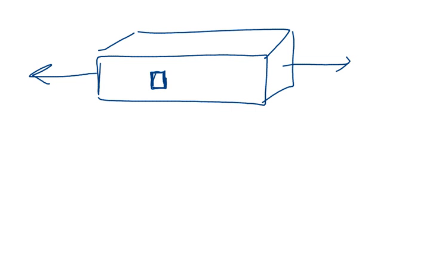But if I happen to set up my coordinate axes a little differently, then I might end up with both a tension and a shear stress. I end up with both normal stresses and shear stresses. So it's a matter of perspective, but when you have something very simple like a rod in tension, then you're just going to set up your axes to match up with the direction of the force.